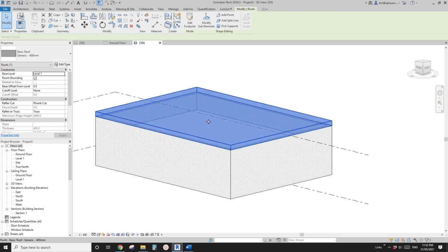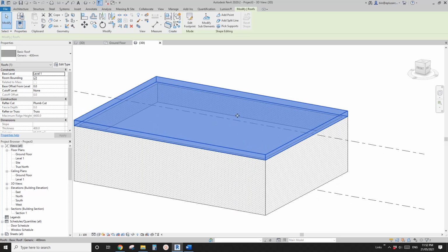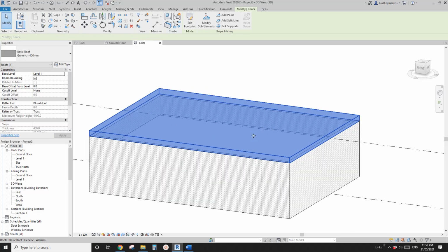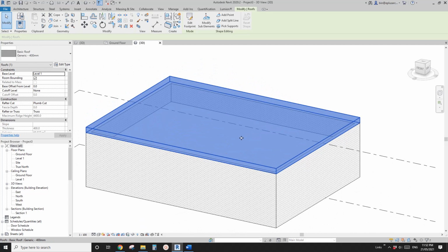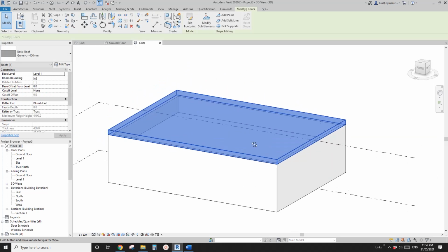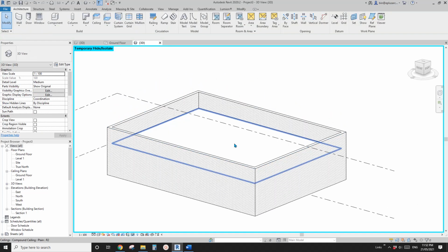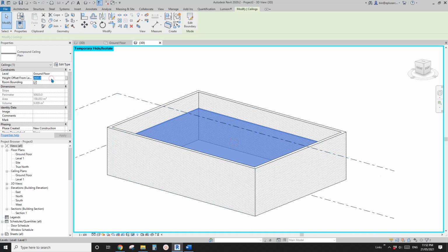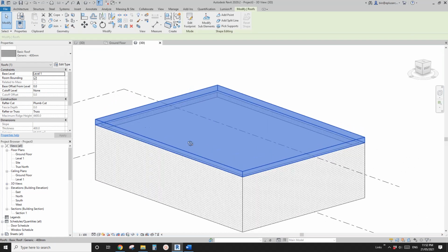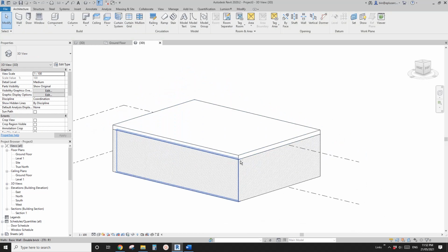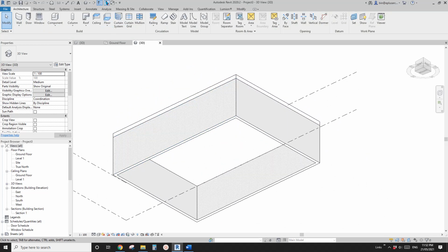Of course you won't have a real flat roof. You will always have some slope for drainage. So actually, let me change the ceiling height. Maybe I'll make it 3.9, maybe 3.6. So there will be some space between the roof and the ceiling.